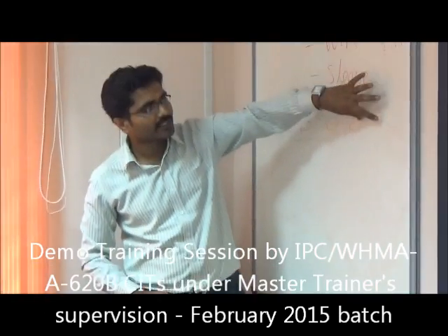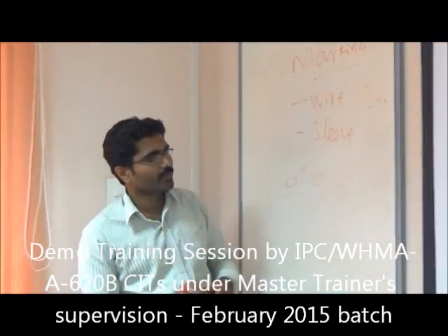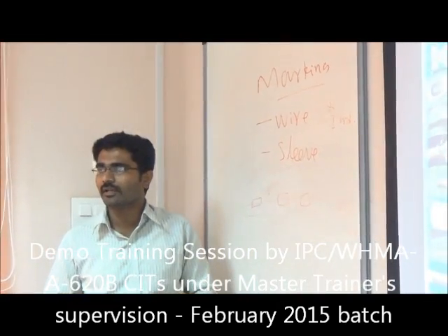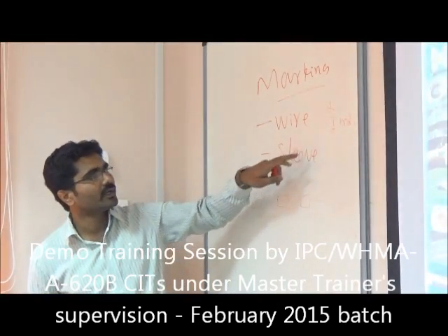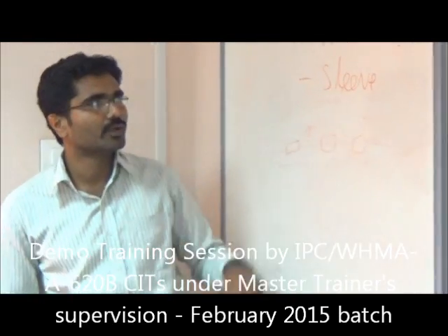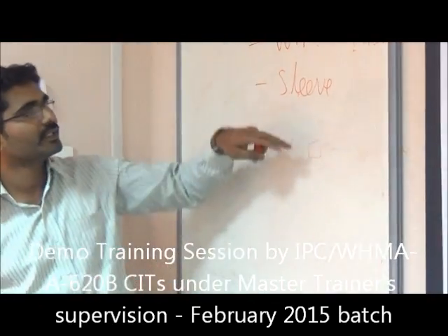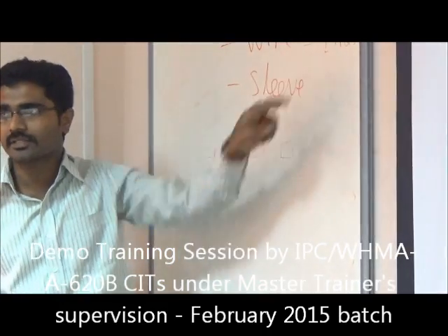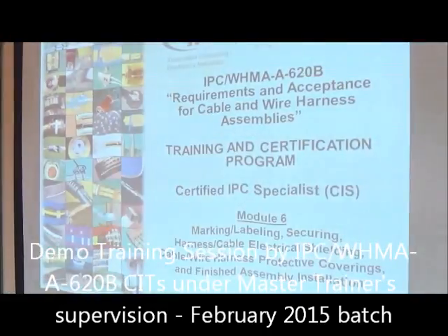At the termination end, in some places we can't see the number, and either we have to rotate the cable to see it. So based on that, they will tell us to use the indirect sleeving on both termination ends. For that purpose, we use the sleevings. In the sleeving also we have hot stamping as well as laser print. Is it understood, what I explained?